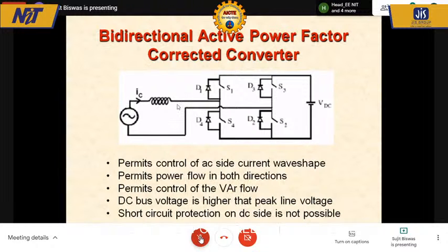So there is a lot of instantaneous difference between the voltages. So harmonic currents will keep flowing and they have to be limited by the reactance that is offered by this inductor. Therefore, the inductor is essential on both the parts. If you want to operate this converter as a rectifier, the inductor acts as the boost element to supply the energy boost. And if you want to operate it as an inverter, you can send power out using this inductor, which works to serve as a current filter.